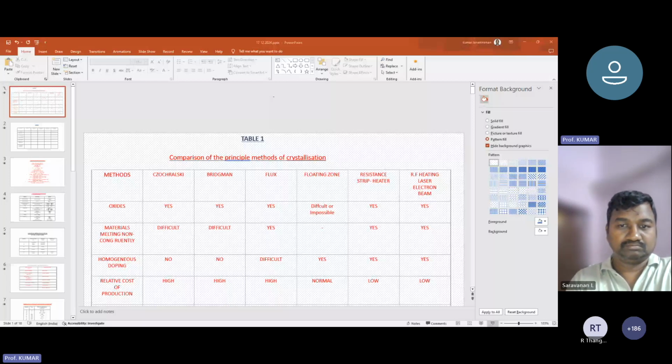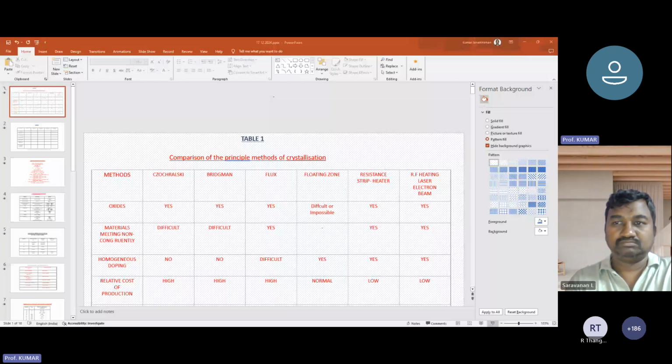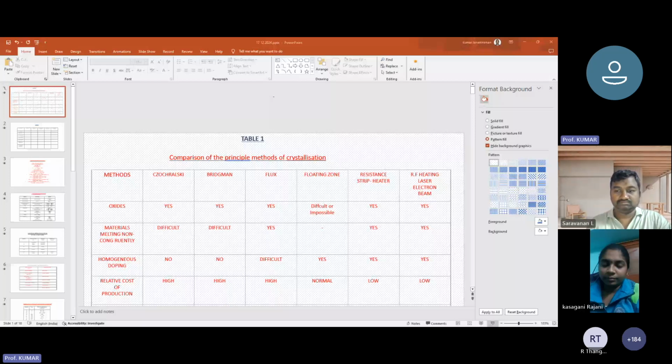And the second important thing is, whenever you want to fabricate a device, the device is fabricated on a given orientation. You would all have done a basic understanding of solid state physics, where you are given a problem of Miller indices. Identifying the Miller indices, you also identify the crystal planes, and you do that on paper. But when it comes to reality, you have to understand how to orient a material and then get the corresponding crystal plane. With that crystal plane, you can fabricate the devices, because there are various aspects of device fabrication. One such is what is called the attachment energy, or the subsequent layers which are grown for device fabrication grow very well in a given orientation.